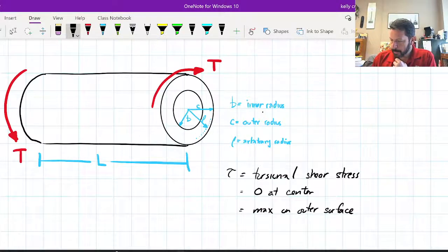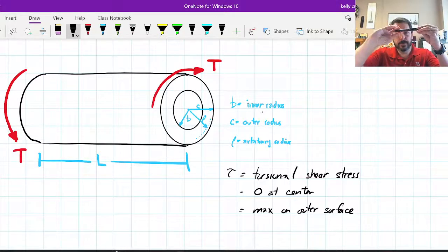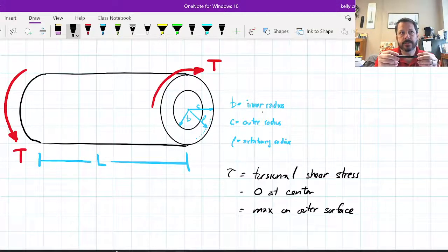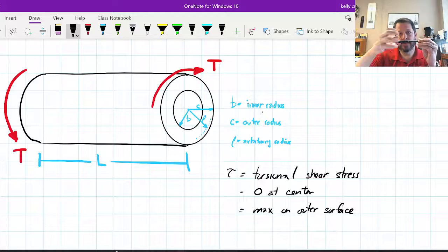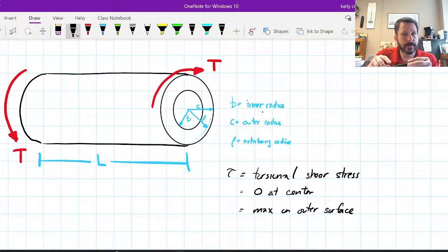All right, I think that sets us up with all of the variables that we will currently need. There's one more. I don't think I want to talk about it yet, though. It's going to be called the angle of twist. So when you're applying a torque to some shaft, it might rotate. It might spin and deliver some power somewhere. But even as it's rotating, it might also twist, and we can calculate that amount of twist too. A spring could actually do that and store energy, or a shaft could do that and just twist, and maybe it twists too far or whatever.